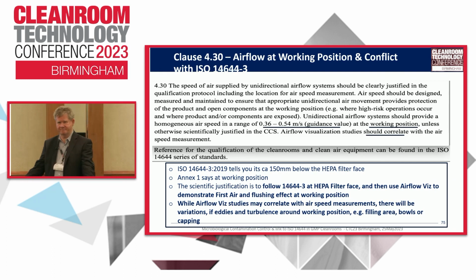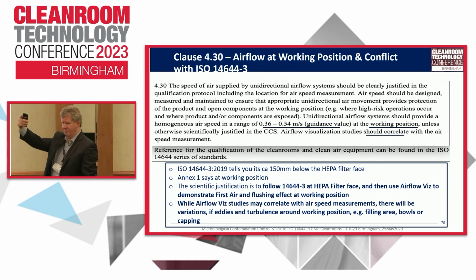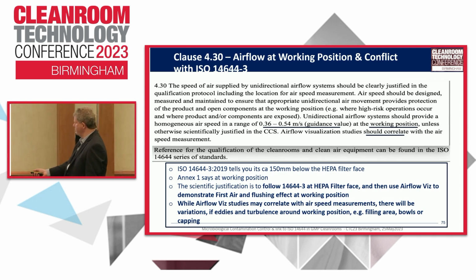It's unidirectional. It comes down. There's no particles in here. You show airflow visualization over the working position. First air and flushing affect the working position, and while airflow vis studies may correlate with air measurements, there will be variations if you have eddies and turbulence around the working position.